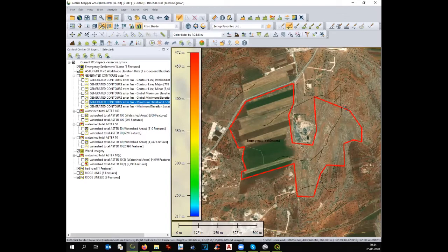I have a question. Why is this a ridge road? Say it again. Why is this considered a ridge road? Because this is the top of the mountain, let's say. If you have a smooth hill and you put the road on the top of the hill, this road doesn't need any drain because water automatically flows on the left side, on the right side. So this road needs less construction works.